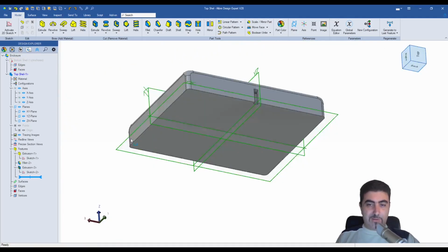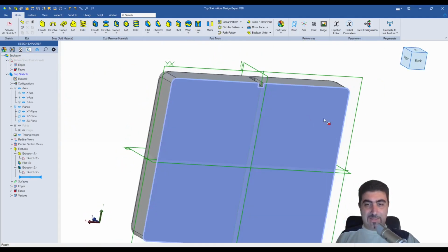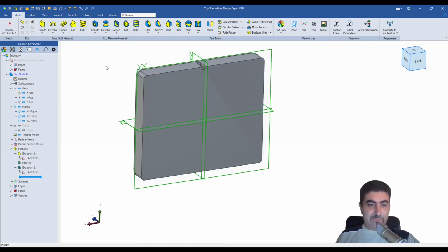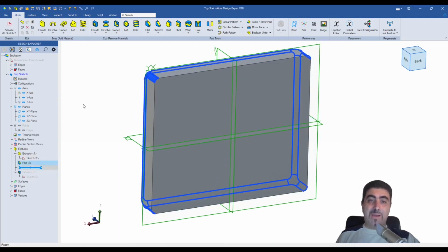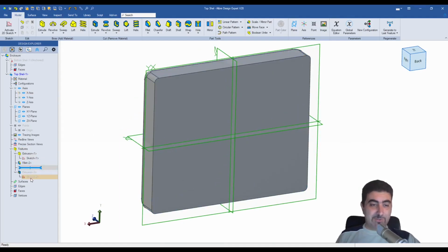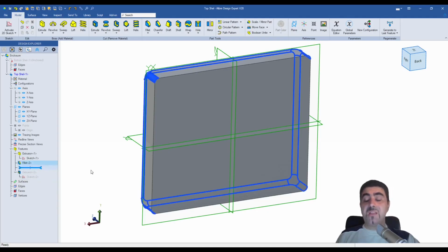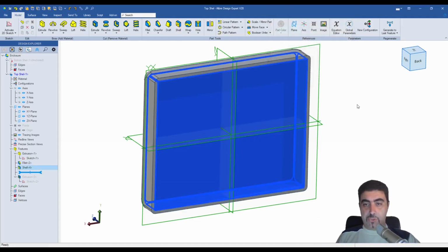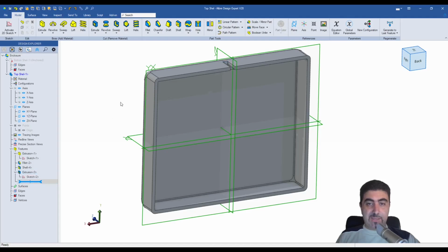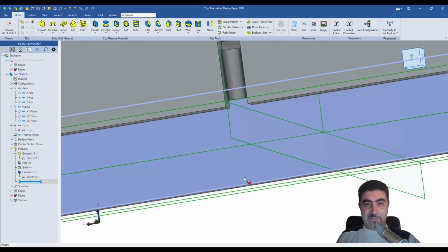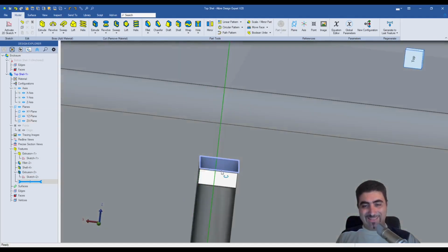So first of all, oh man, I didn't shell before I did all of this. So we're using a parametric CAD software. So this dog bone here, this line, is our time travel lever. So we pull the time travel lever, we go back into time before our extrusion, and we make our shell. And then we come back in today, and we see that we broke everything.